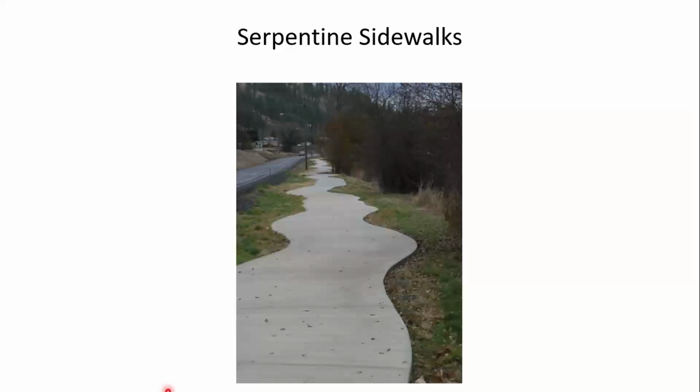I mean, they have a really curvy route here, a lot of extra distance, maybe more difficulty in following the route. Same thing with somebody in a wheelchair. Might be difficult to take a straight line path here. They're going to often be trying to turn or adjust their alignment, which requires extra energy. But then also, just think about maintenance: if you're trying to clear snow from this type of sidewalk with a skid steer or a tractor or something, or sweep the sidewalk, it would seem to make it more difficult.